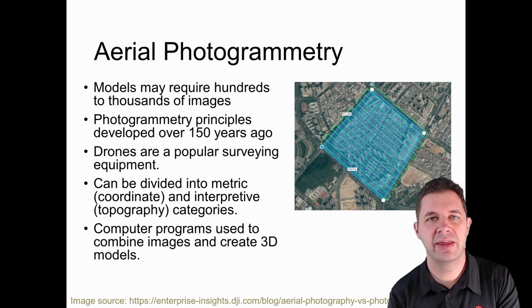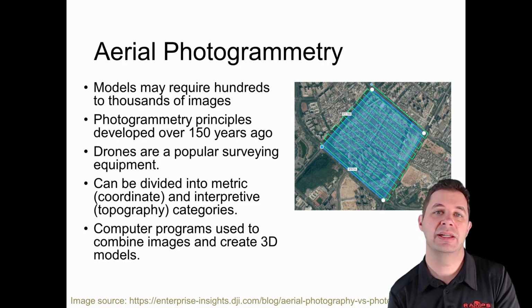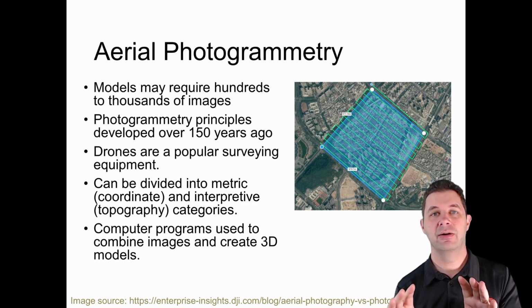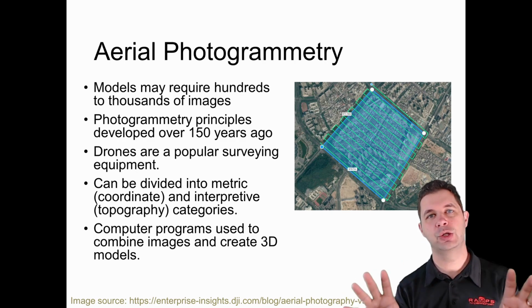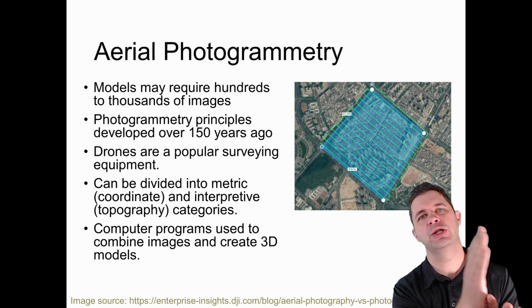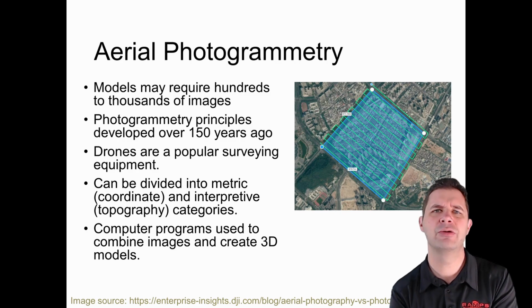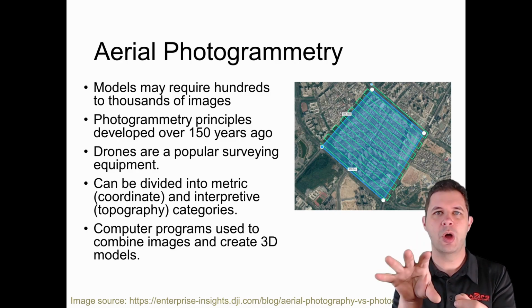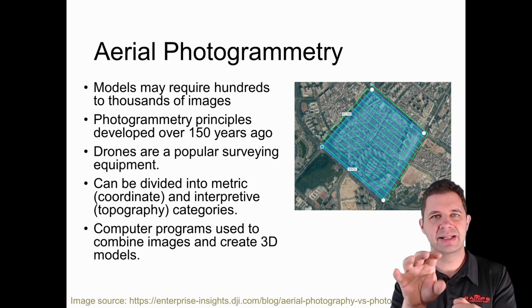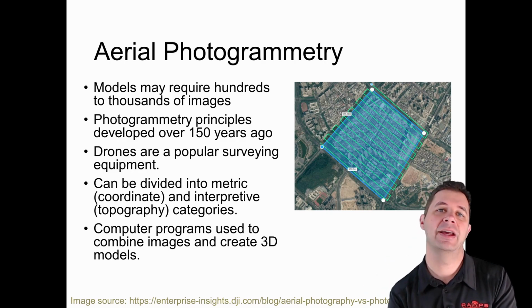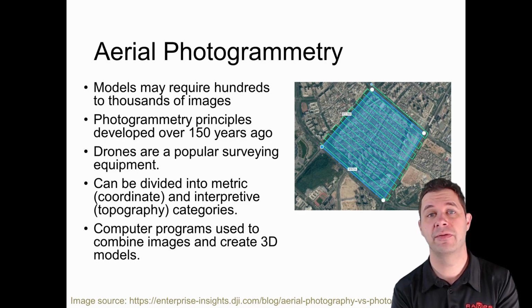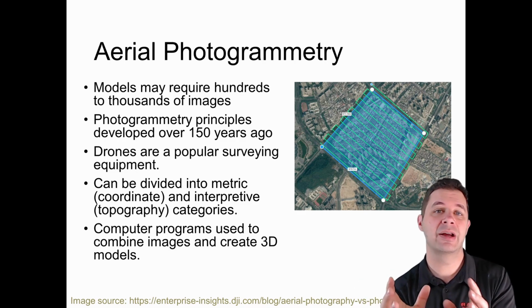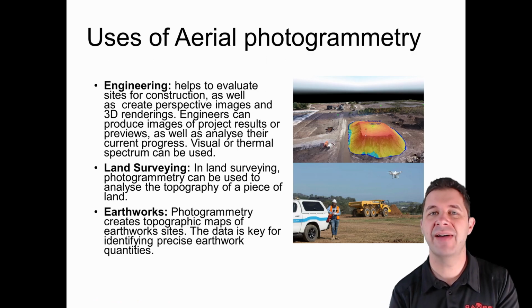We've got computer software that we use for two different applications here. One application is actually designing the flight path of where these drones are going to fly, where all the pictures are going to be taken, because we might have hundreds and hundreds of pictures, and you don't really want to sit there flying your drone and stopping it every couple of meters and taking a picture. So that's one application of the software, and the other application is stitching these all together and creating our three-dimensional model.